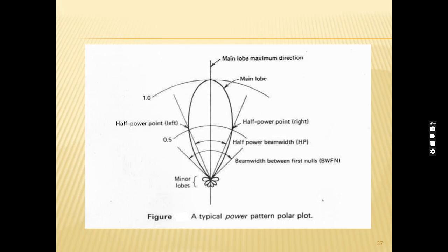The field and power patterns are normally plotted with respect to their maximum value, that is called the normalized field and power patterns. Also, the power pattern is usually plotted on a logarithmic scale or more commonly in decibels. The scale is usually desirable because a logarithmic scale can accentuate in more detail those parts of the pattern.